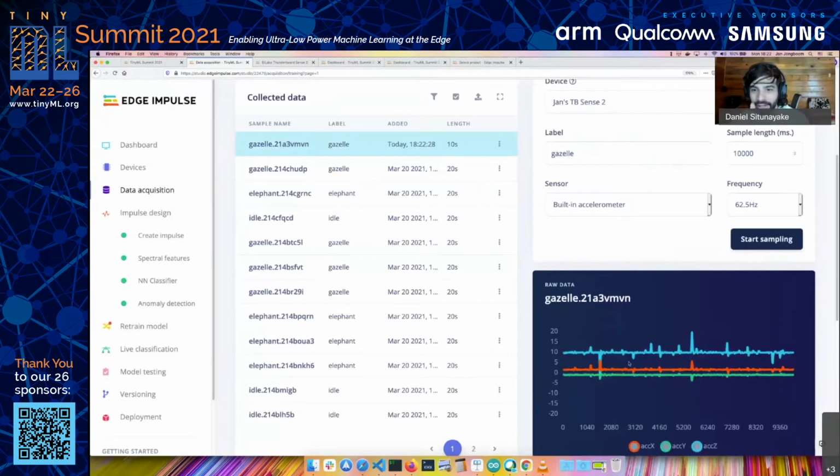One thing I wanted to note while Jan collects this data: if you were having any issue dragging that binary onto the mass storage device, try resetting your board. If you ran into any problem where it just quickly flashed on there and didn't do very much, try resetting the board and that might help. The LEDs should flash on the board when it's happening. And if you have any questions or something doesn't go right, there's a link to our forum in the workbook, and we have our user success people monitoring that. If you need quick help, that is probably faster than the Q&A because we can't really help you debug right now.